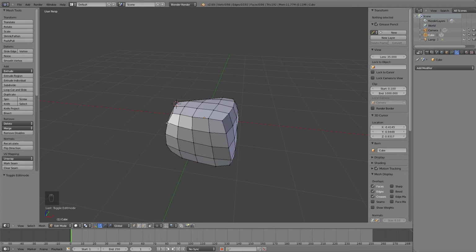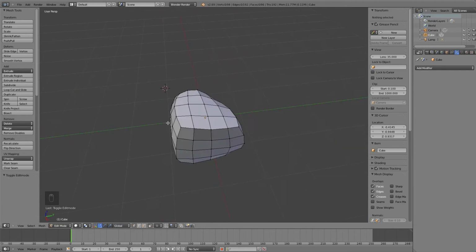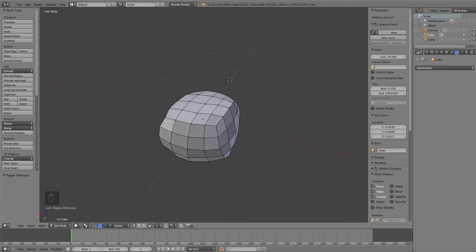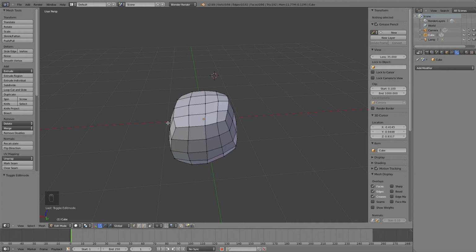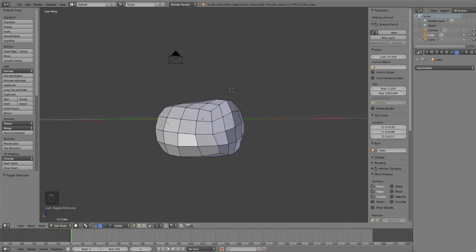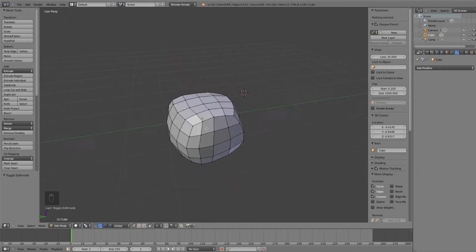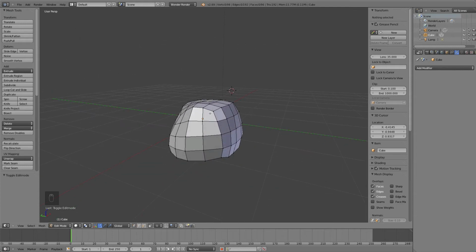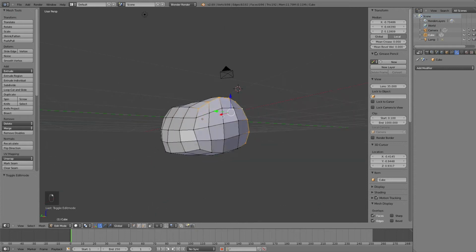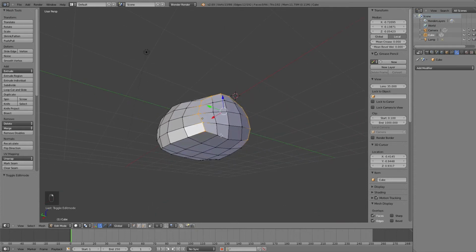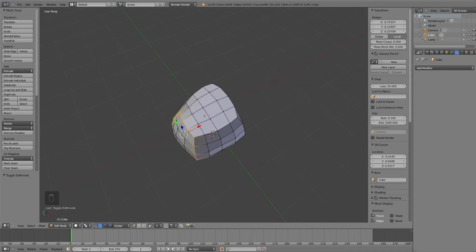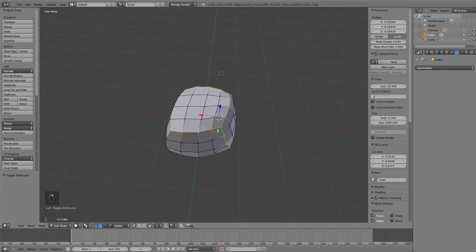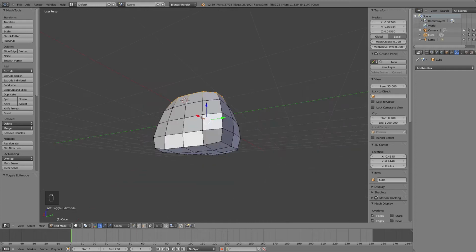Now, what you want to do is texture it, and texturing can be hard because seamless textures are very hard to repeat over and over again when it's a rounded off object like this. So what you want to do before we UV unwrap this, which is basically outlining it so that you can wrap a texture around it in Unity.